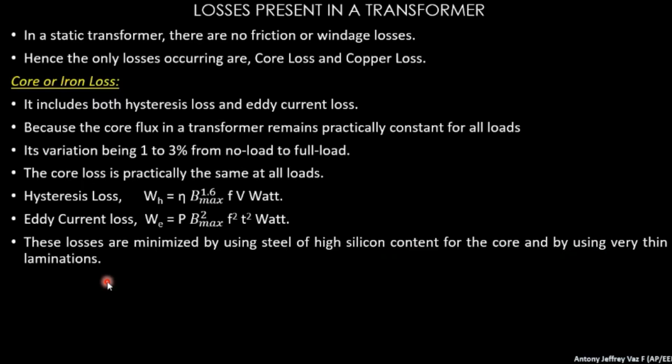So, core loss is due to the hysteresis curve. This hysteresis curve should be minimum. So, when you are searching the chemistry, you can see the material, that is the silicon content present in the steel. This material has a very low hysteresis loss, so this material is chosen for the transformer core windings.